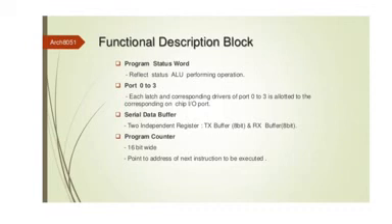At the time the fifth line is being executed, the program counter already points towards the sixth line, so that it will be fetched next after the execution of the fifth line. So listen to this line properly: the PC is automatically incremented to point to the next instruction in a program sequence after execution of the current instruction.